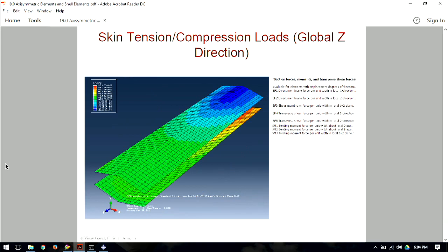So here we were talking about line loads. My NX values, so these are my compression loads and my tension loads, and you can see them being plotted on the elements themselves. Here, Abaqus calls them section forces. In this particular case, it's SF1. So you have to really read the documentation and know what you're reading, because you can transform these into any direction you want.